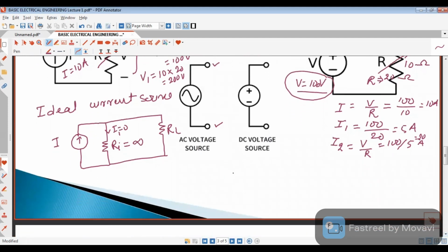Let us see for ideal voltage source how we can write. Suppose this is our voltage source drawing here. It has also internal resistance that I put either upside or downside, does not matter. Here suppose its internal voltage is E and this internal resistance is R. So in this case its internal resistance is 0. So whatever voltage, suppose if this voltage is 10 volt, so we will get here 10 volt as output.